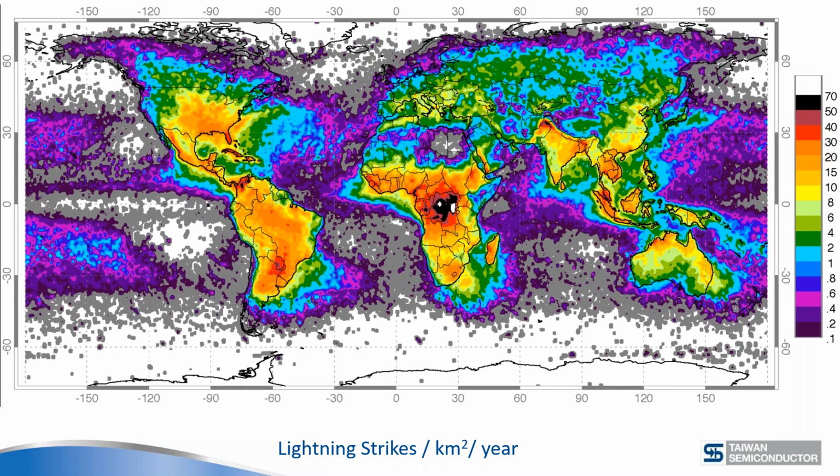And then you're going to see the die size of each different supplier show up in field failure rates and that type of thing. So it is possible to have field failures with TVS diodes because the lightning strike does not always follow the norm. That's something to keep in mind.